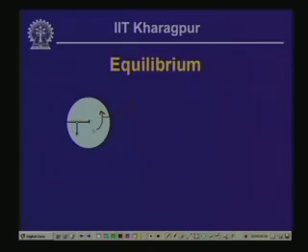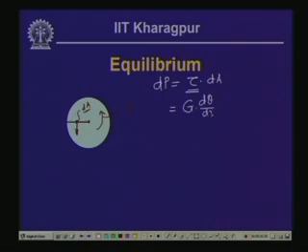Now, this is the center of the cross section. Let us take an element of area dA. The force acting perpendicular to this radius is equal to the stress times the area. So, the force acting on that small element, dP, is equal to the stress tau times area dA, and we have already seen tau is equal to G d theta dx times rho.